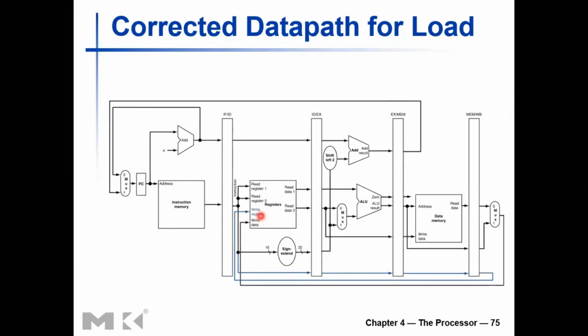that will not create an issue, because at the end of the clock cycle, the read data will have stabilized, and because you spend some time here for the instruction to decode, and the writing will happen in parallel to the writing of the pipeline register. So by the time the address propagates here, you have already updated the writing register. And at the end of the clock cycle anyway, these values would have stabilized at the new up-to-date value if you are reading the same register that was written to in this very stage at the same time.